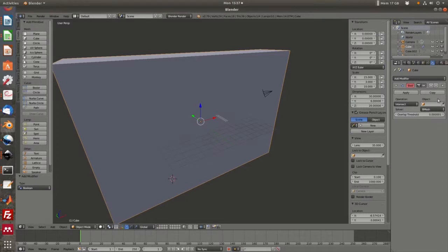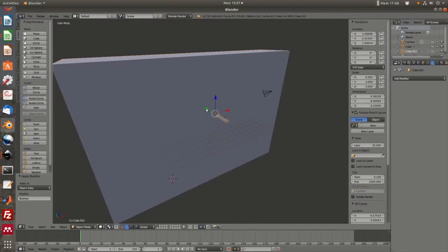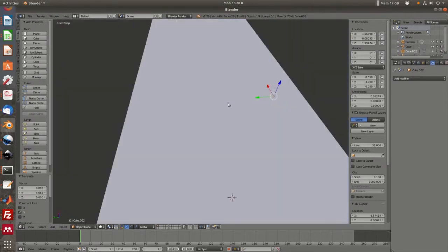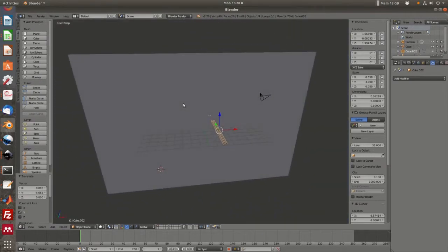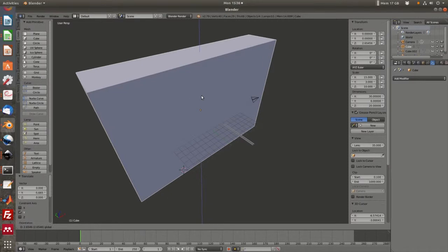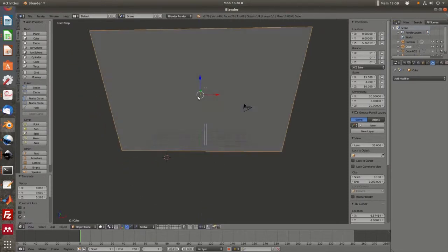We're going to use a difference operation, and the object we'll use is cube number 2, which is our electrode. Once we've applied that, we can see that we've got the indentation that we want into our tissue, and those faces there will be the faces that we'll use as the current source in the finite element model.